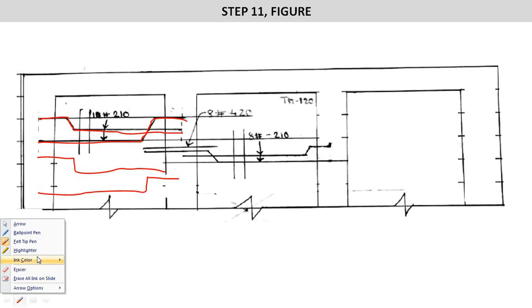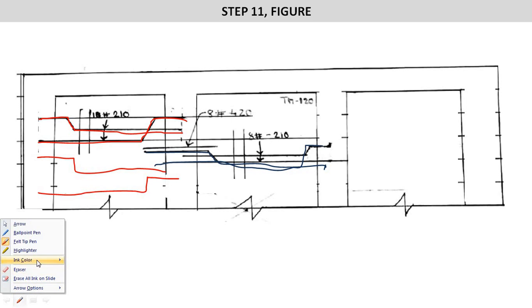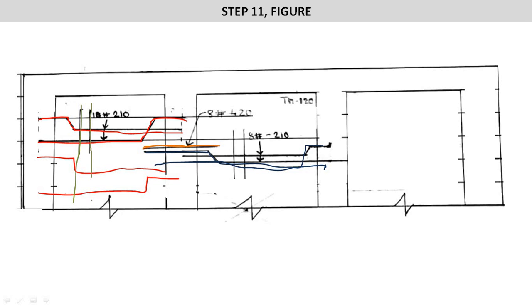On this second span we see the bent up here, so it will be bent over here, and another bent up is seen over here. Like this, and between them the extra top bar is provided, and also to connect those main bars we have to provide the distribution bar. Here it has been shown in this direction. There are distribution bars 8 dia, 320 center to center or 350 center to center in this direction.